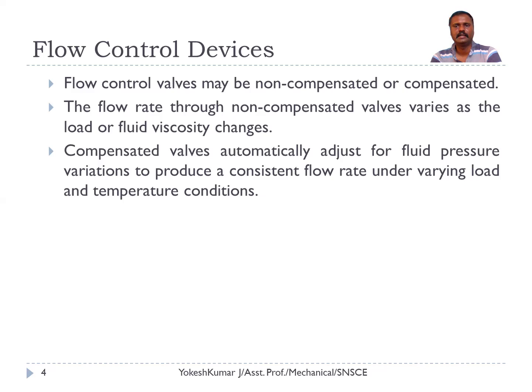in deciding the flow rate of the fluid. Say, for example, initially we are starting the machine. All the machine parts are at atmospheric temperature. Therefore, the viscosity of the fluid will be more and the flow rate will be less. Imagine the machine is operated 8 hours or 12 hours continuously, the machine is heated up and the temperature affects the viscosity. So therefore, the viscosity of the fluid reduces. In that case, flow rate increases. So the machine operates at very high speed.